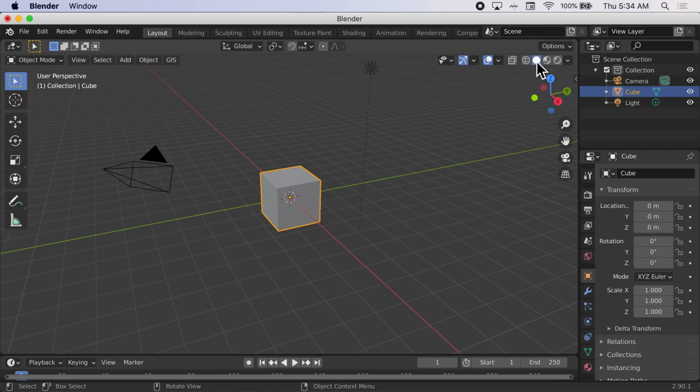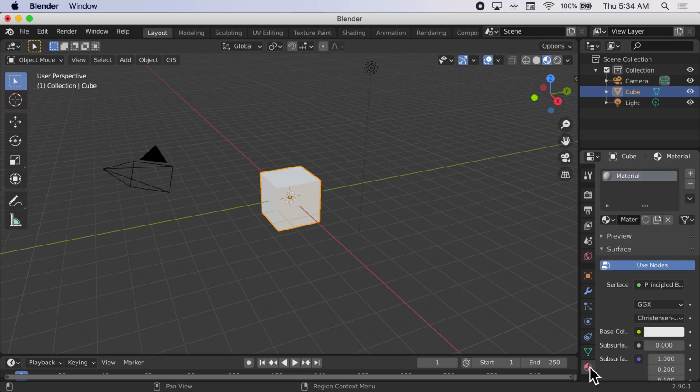This is our shaded, just a basic shading, and this is like the development shading mode, and that's the one that we're going to use. So if you go over here and select this particular one, it puts it into dev shade mode, which at that point starts to consider what materials you have, what materials you're using. So if you go down to the right over here and you click on this circle, this is the material properties. So this circle right here opens up a different panel. All of these little tabs open up specific parts of this panel on the right.